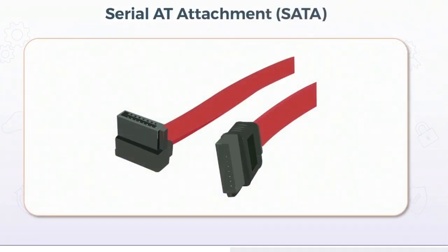The SATA connectors themselves were much smaller than their IDE counterparts, only about 1 centimeter across, and each connector was keyed so that it couldn't be inserted incorrectly. And in most cases the cables were red, but that isn't a standard, and usually the connector for the motherboard had a straight connector, and the connector on the drive end was 90 degrees, which simply made it easier to make the connection and have less cables sticking straight out from the back of the drive, although some cables were straight on both ends.